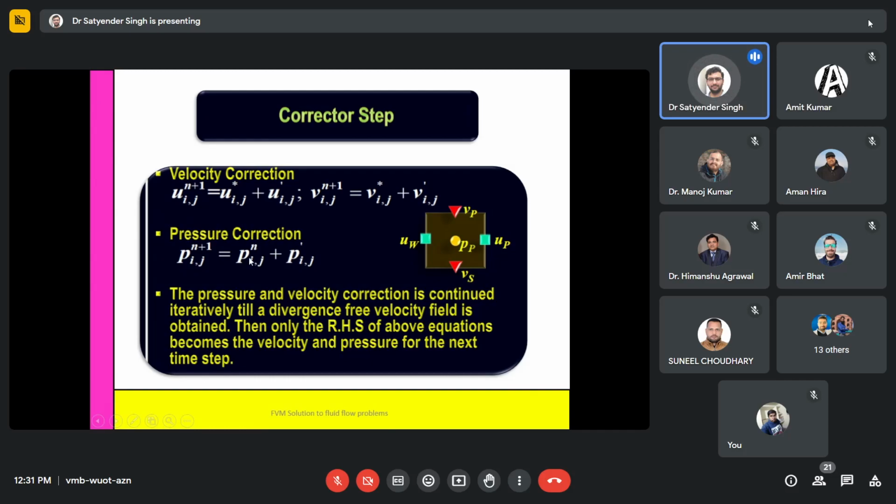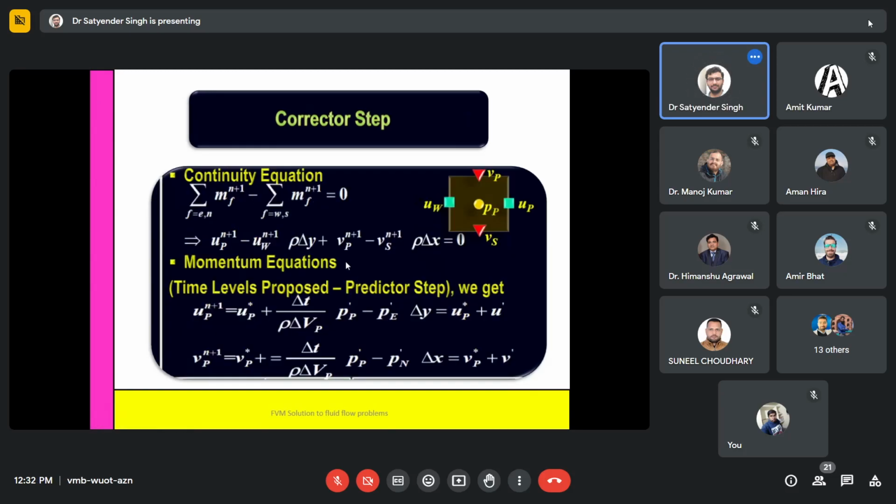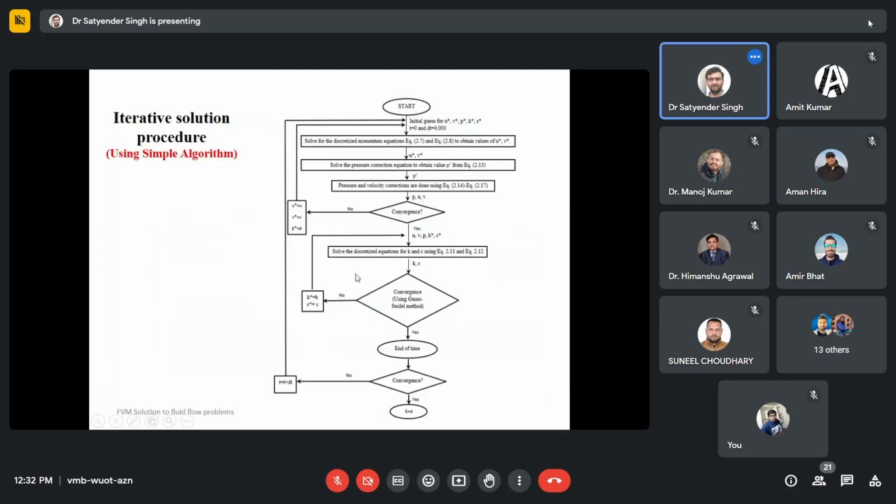The pressure initially assigned to the computational domain is generally p equal to 0 at all cell centers. And this is the new value for pressure you guessed just to start the computation procedure. We keep on doing this until continuity is satisfied to a particular level of error. So in continuity we make a check, and we keep on calculating until the solution has converged. And this is now the SIMPLE algorithm.